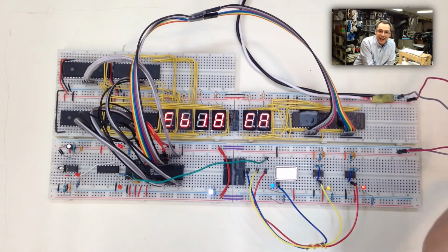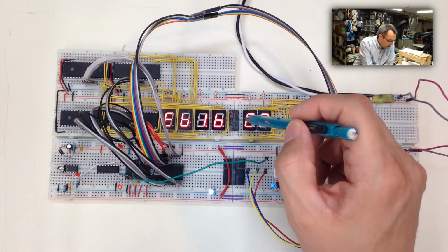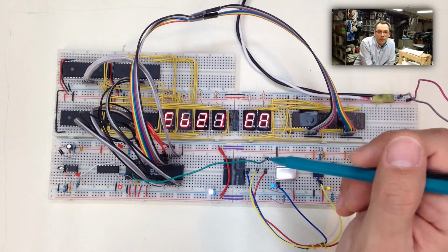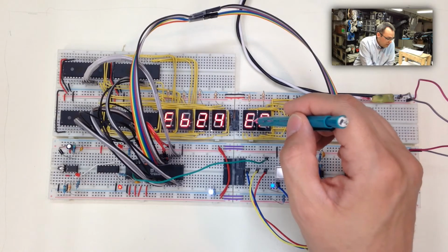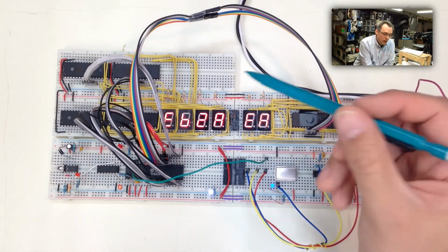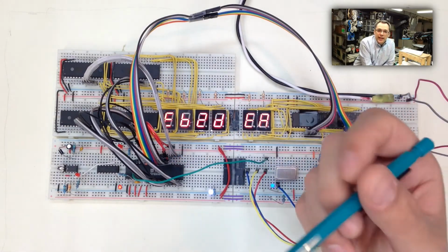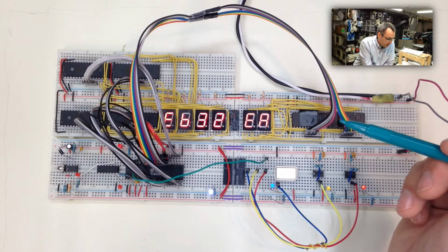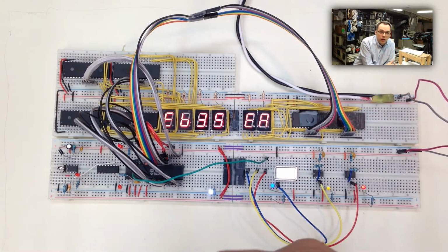Now, why did we select EA? Well, those out there that know the 6502 know why I've done that. The EA is the instruction for the 6502 to do nothing. It is a no operation instruction. What this means to the CPU is to do nothing, go to the next instruction, and execute the next instruction. Since we always have EA on the data bus, the 6502 will continuously and forever execute absolutely nothing over and over again forever. What does this allow us to do? Well, that allows us to set up the computer in a very simple free run mode that allows us to see what's happening on the machine. And we can see that it's doing that.